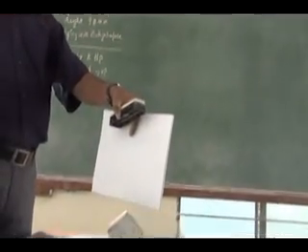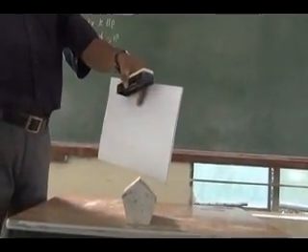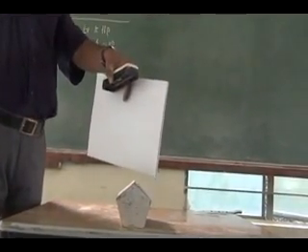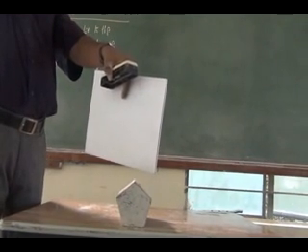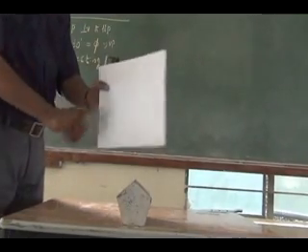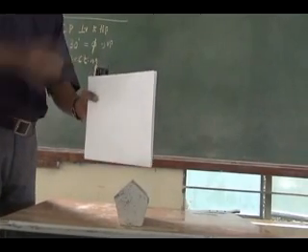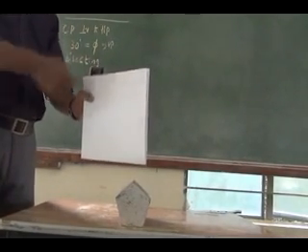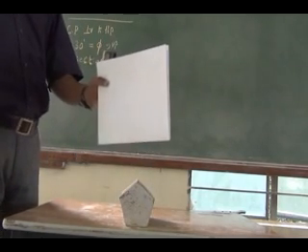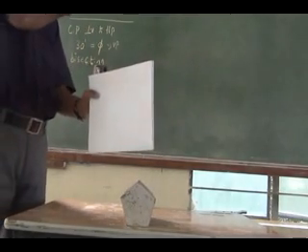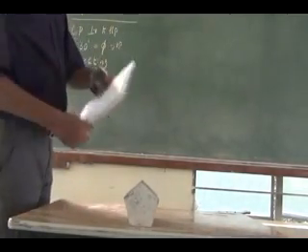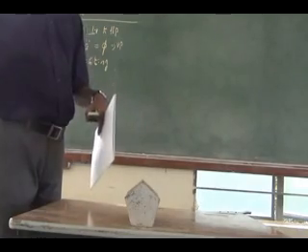Now, what view will we get first of all? This view is the top view. Then what view? The front view will be a sectional front view. So in this orientation I have to draw the top view, then I have to get the sectional front view, then I should get a separate true shape. So you take the problem, draw the top view, sectional front view and true shape of section.